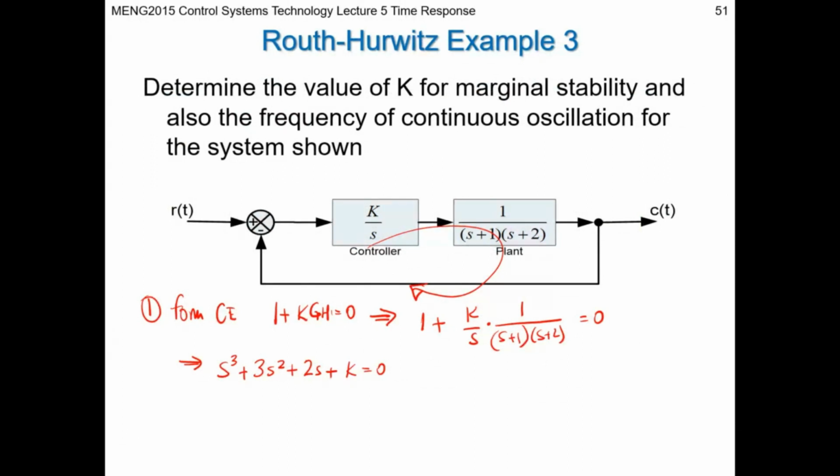And what we're going to do in this instance is basically determine what value of k will cause the system to be stable or unstable. So you notice k is here. K is again a multiplier. So whatever our error is here, our error is multiplied by k upon s. Because it's something upon s, this would be called an integral controller.